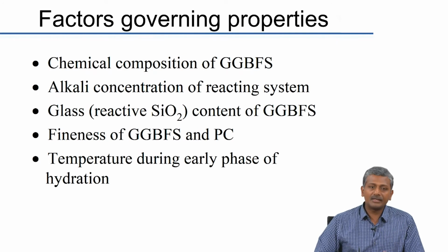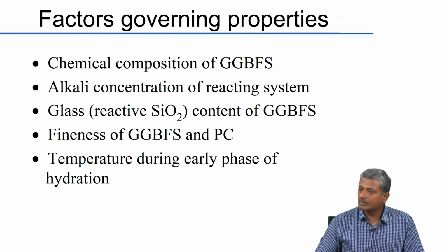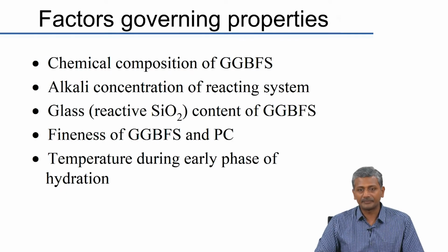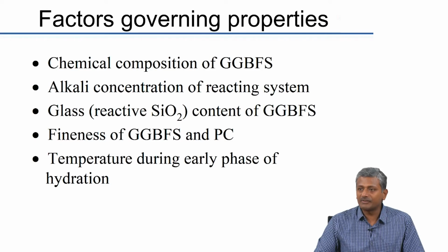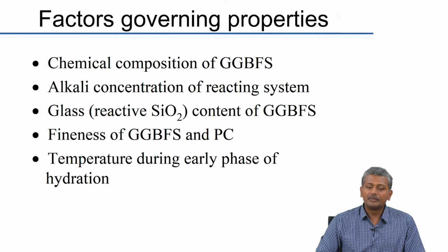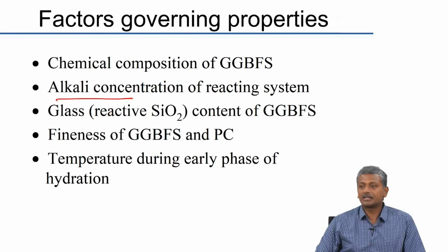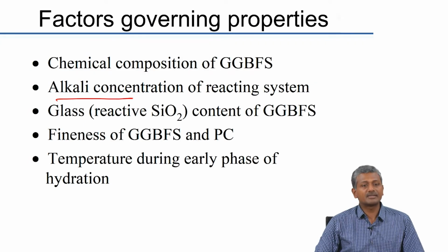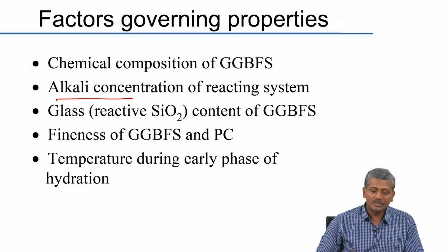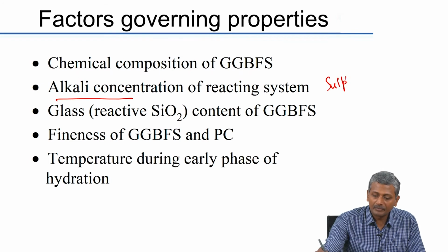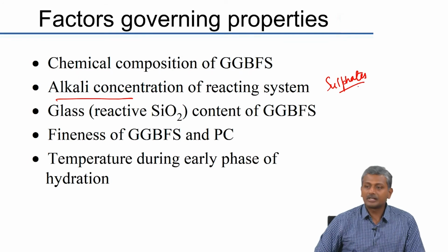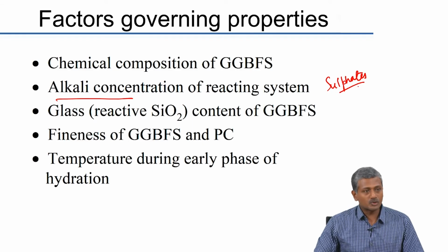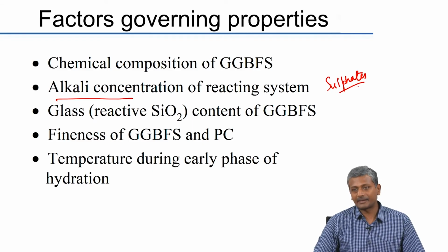Now obviously slag is a latent hydraulic system. If you let slag react on its own with water, it may take a substantial period of time before that reaction gets anywhere. So if you do some activation of the slag, it leads to a faster reaction, and activation typically is happening primarily because of the alkalis that are present in the system. For example, the alkalis that are contributed by the cement and also the sulfates that are contributed from the cement. That is basically gypsum that is present in your system also acts as an activator for the slag.